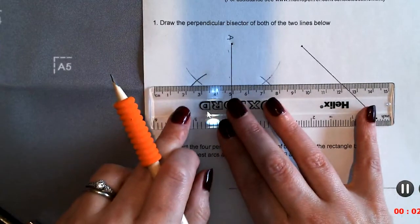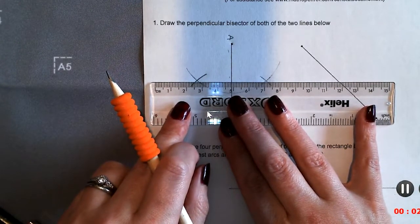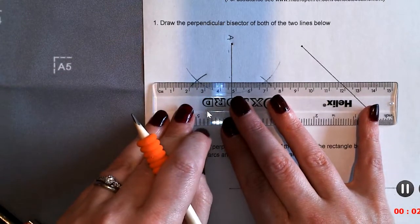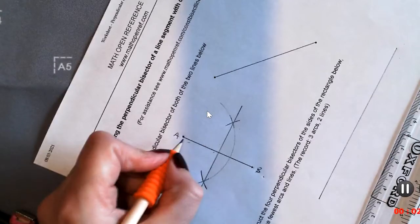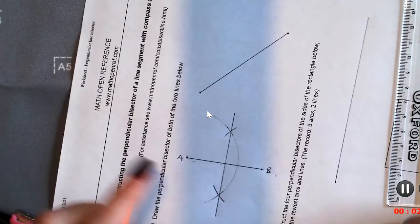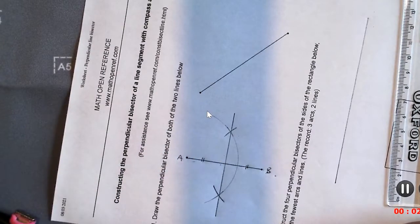So what you do then is you place your ruler beside the two crosshairs, and when I say crosshairs I mean where the two lines cross, right in the center, and you put a line directly through them. And what it does is it has now bisected that line AB in half, so the length of that line is exactly equal to the length of that line.